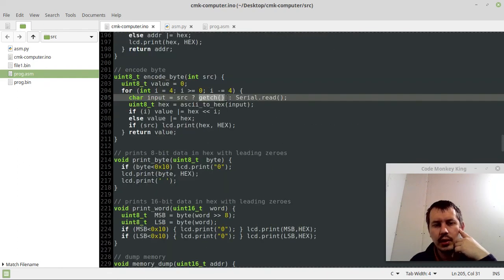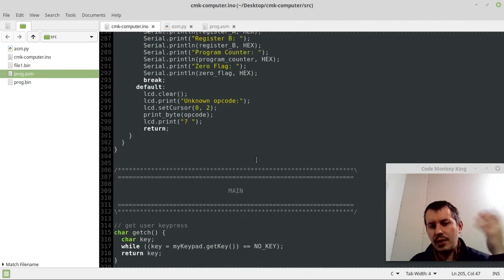In the case of serial communication, we just read a single byte, the next byte of the incoming data, from the receiver buffer. No matter what the source is, we just need to keep track of whether this is the first character or the second one, and formulate a byte from that. That's pretty much all about it.